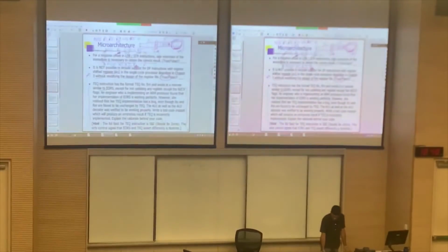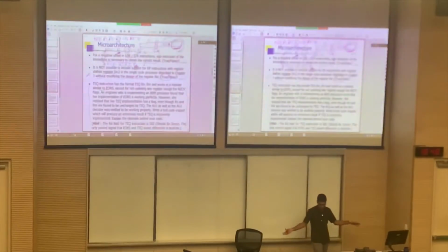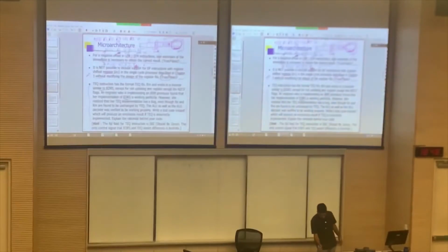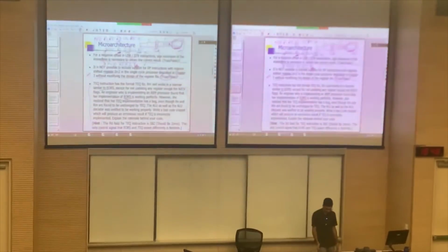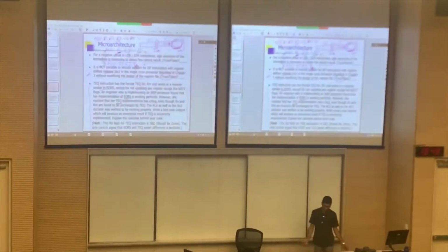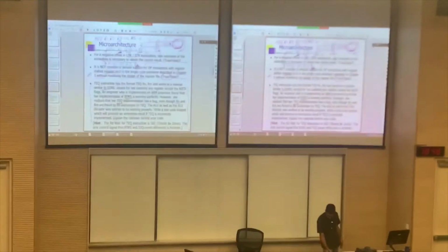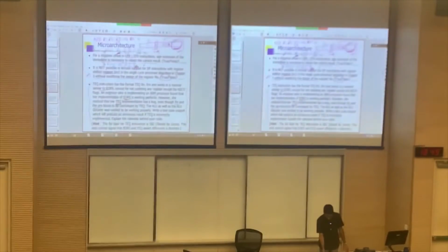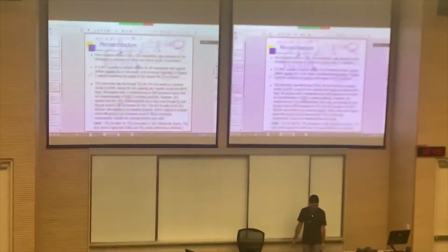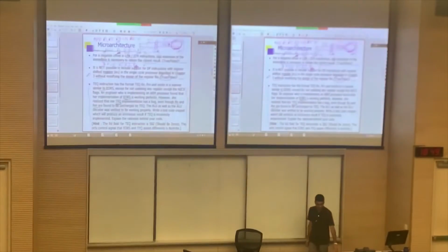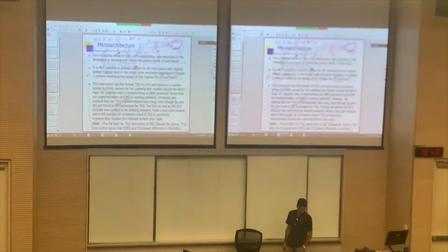An engineer who is implementing an ARM processor found that the implementation of EORS is working perfectly, but TEQ has a bug. Okay, even though RM and RN are found to be unchanged by TEQ. The ALU as well as ALU decoder was verified to be working properly. Write a test snippet code which will produce an erroneous result if TEQ is incorrectly implemented.